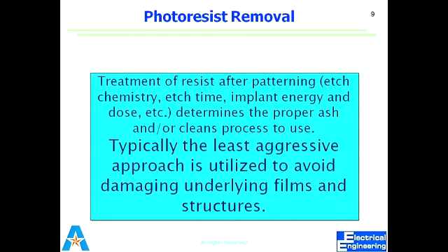Yes, that is the power. But you have good control, and it is a very simple process. You have control over which gases you want to introduce, and the concentration or power of the gas. You can even use more than one gas, a mixture of two gases, to remove material from the surface during dry etching.